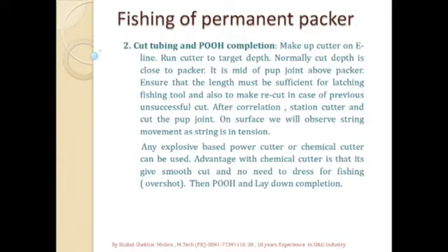And also we need sufficient length for the latching of the overshot above the packer to fish it out. So if we go with the RCT chemical cutter, then it gives a good smooth cut, and in that case we need not trace it.